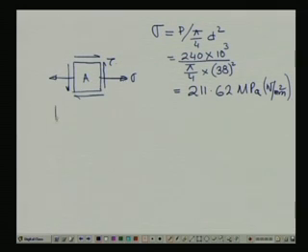So, just have a look through the Mohr circle. This is an explained behavior. This is shear stress, it is negative, creating an anti-clockwise sense as per our notations. So, we get one value like this, and on the other plane there is a positive shear and no normal stress.